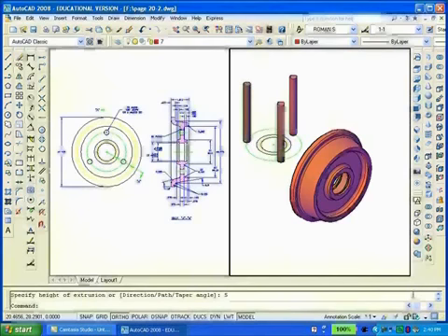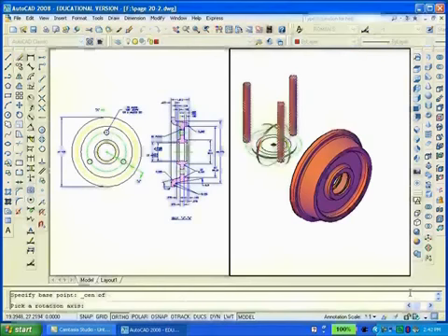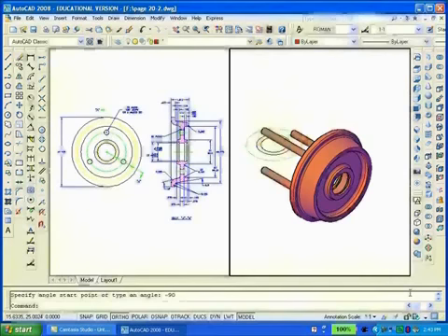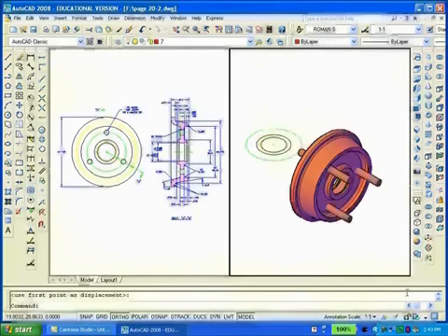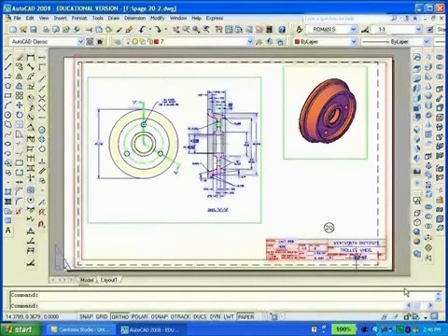Now I'll use the 3D rotate command to rotate the 3 cylinders 90 degrees clockwise. I have to move the 3 cylinders forward so that they penetrate the wheel. When I subtract the cylinders from the wheel, the 3 holes will be formed. The solid is completed, so I'll click on the Layout button to get into paperspace and set up the desired viewports. When the viewports layer is frozen, the detailed drawing is ready to be plotted.